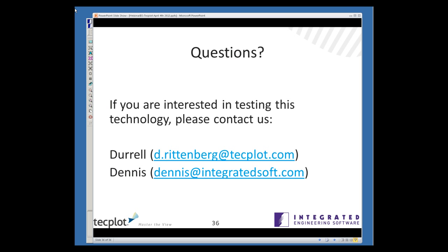The question is, can motors be simulated using rotational symmetric analysis? And no, because there's no such thing as a torque in rotational symmetric analysis. So normally motor designers are using 2D analysis for conventional radial flux motors. If you have an axial flux motor, then you have to do a full 3D analysis. Okay, thank you, Ken.